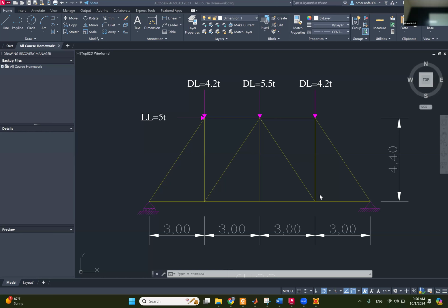Well, in real life, they have. Like if you build a truss system, all these members are going to have it, but what is the value of this bending moment? The bending moment is very, very small, so it can be neglected. So that's actually, we talked about this before, when to neglect and when not to neglect. So that's some few things that we need to talk about before starting structure analysis on any software.